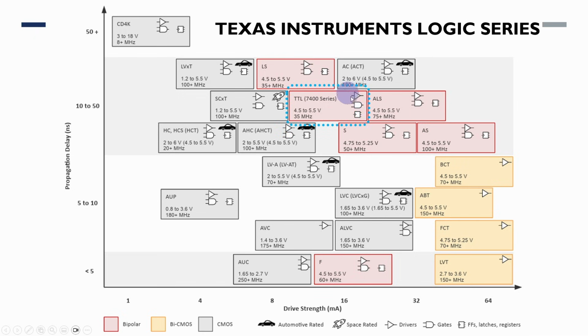If we look at the beginning here, the first TTL series was sometime around 1965-66. It generally became available to hobbyists in the early 70s. The first electronics magazines with 7400 series chips for sale were in about 1970-71, I think. This needed to work off a pretty precise voltage, really as close to 5 volts as possible, although it does allow a bit of tolerance.